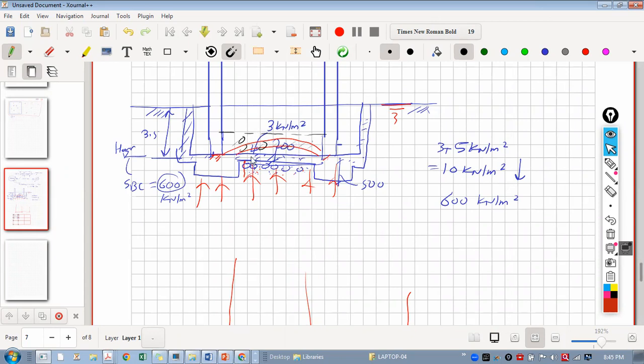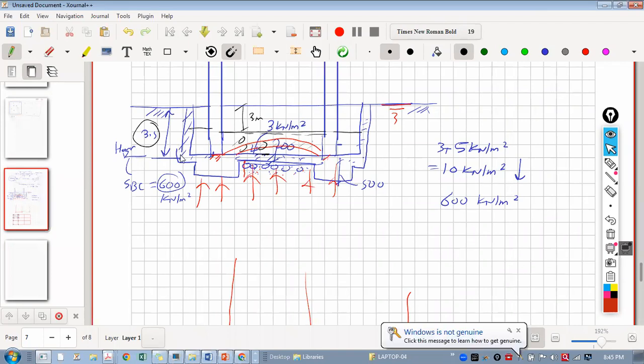In that case only, but see this raft level is important, because then you will have raft here, isn't it? At bottom. Because maybe it is a functional level, na? Because you cannot disturb this level. That is parking level. You can do this way also, or you can design this for 3.5 meter, say, because of water. This is a hard level, right? Hard strata. Footing is embedded right here. So only the slab will deflect.